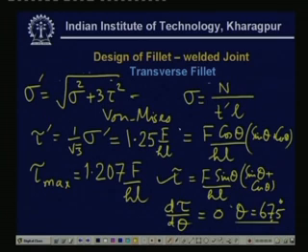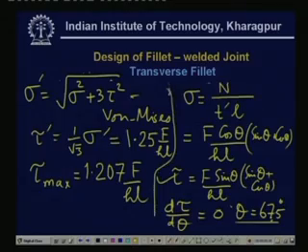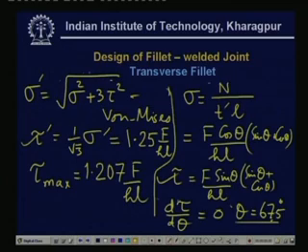So, this I leave to you to calculate, but what is important is that having done all this, what we get is the average value, but it seldom matches with the experimental results. Experiment was carried out with photoelastic apparatus, a photoelastic experiment was done, and it was found that it is very difficult to find any match, that is there is practically no match between the strength of material approach and the reality.